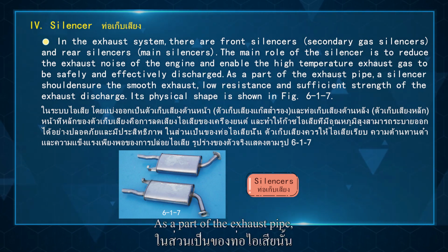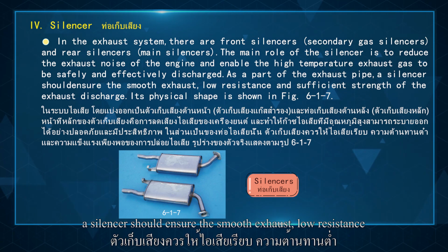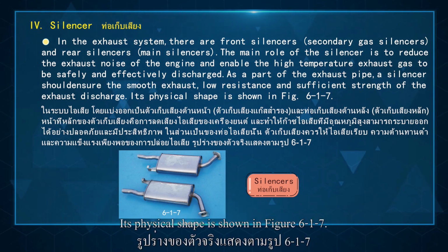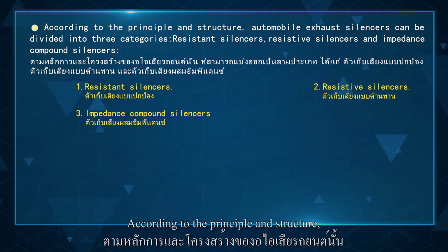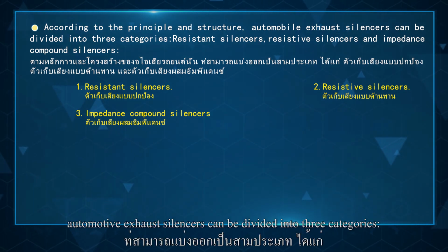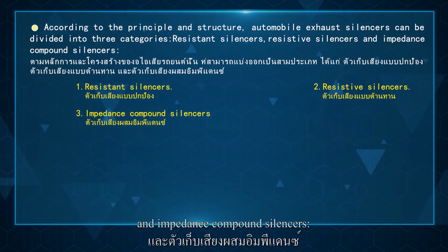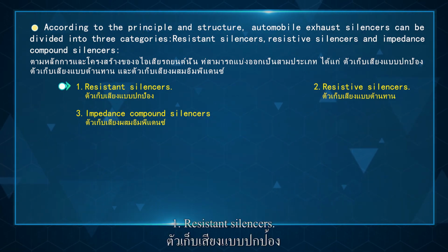As a part of the exhaust pipe, a silencer should ensure smooth exhaust, low resistance, and sufficient strength of the exhaust discharge. Its physical shape is shown in figure 6.1.7. According to the principle and structure, automotive exhaust silencers can be divided into three categories: resistant silencers, resistive silencers, and impedance compound silencers. 1.